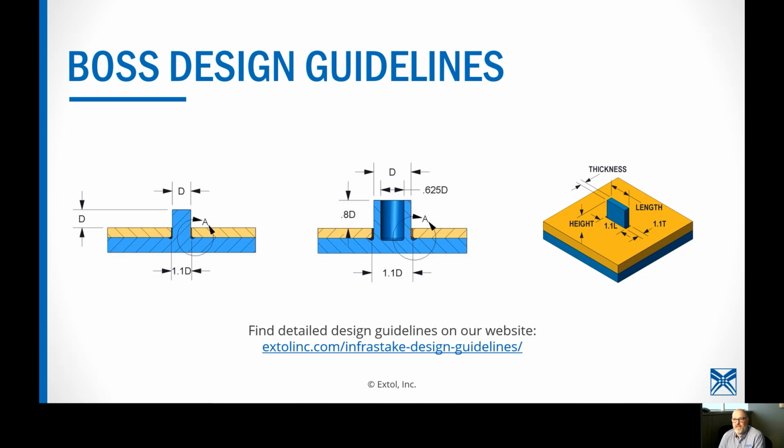I will tell you also that these design guidelines are available on our website. You can click them and download them, exactly what you're seeing right here, but with more detail on it. I've kind of trimmed it up a little bit for this presentation. We also do tab styles, and this gives you a little bit of dimensional thickness for those. The big thing is for tabs, this length needs to be less than 10 millimeters. If it gets more than 10 millimeters, it gets really difficult. It just won't fit.